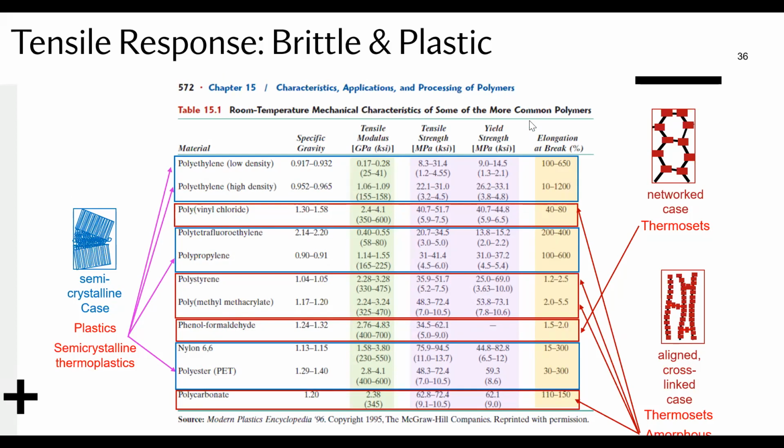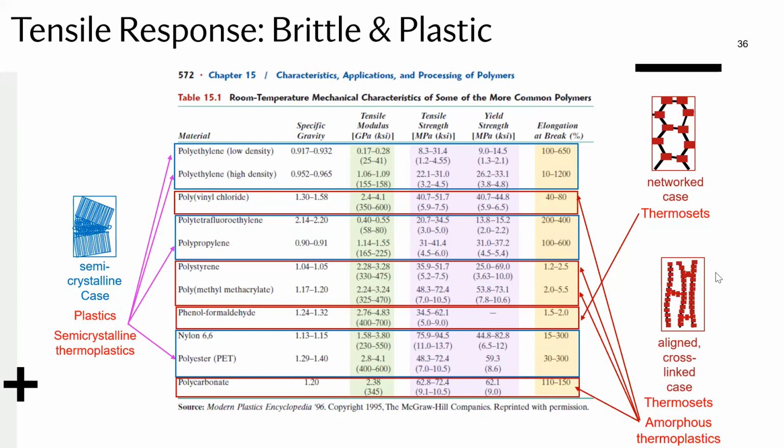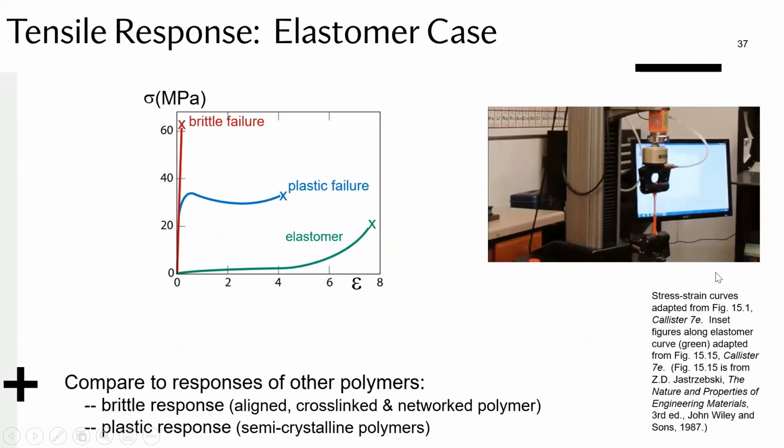Okay, so now we're going to move on to elastomers. And elastomers, as you know, they elongate quite a lot. So you can see here, this tensile test is pretty fun working with these materials. They can go forever. Literally, you can see that this is elongating easily to twice, 3 times, even 4 times its length. And so they go through this rather, I wouldn't say exponential, but sort of up-facing curvature regime.